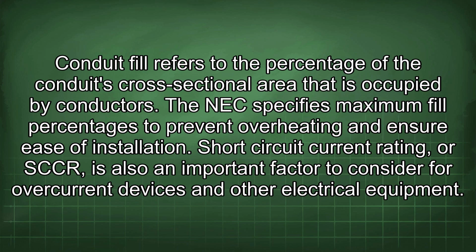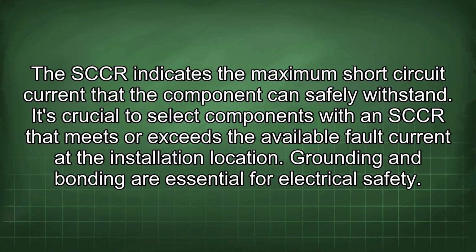Short circuit current rating, or SCCR, is also an important factor to consider for overcurrent devices and other electrical equipment. The SCCR indicates the maximum short circuit current that a component can safely withstand. It's crucial to select components with an SCCR that meets or exceeds the available fault current at the installation location.